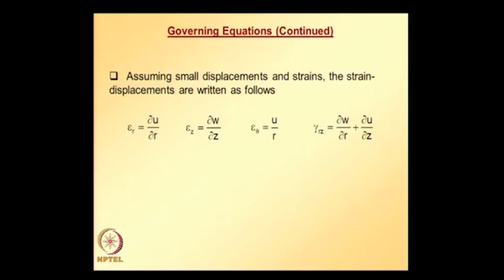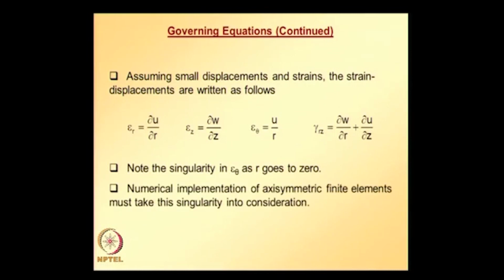Numerical implementation of axisymmetric finite elements must take this singularity into consideration. So, these 4 equations give us the relation between strains and displacements.